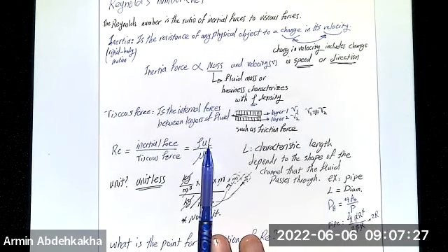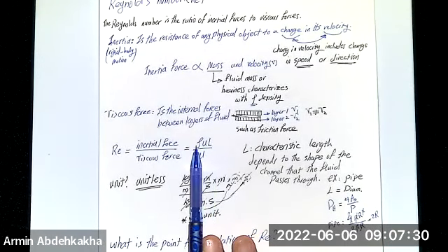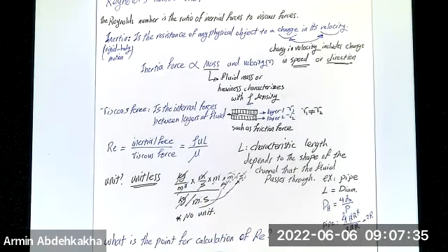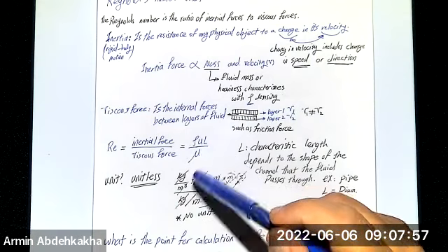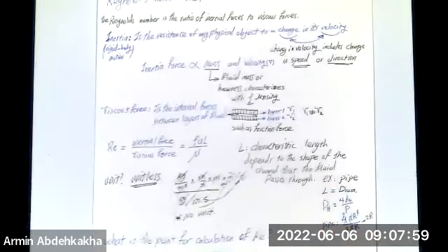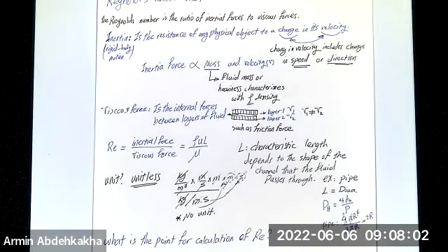If you multiply the characteristic length times the rho, absolutely the characteristic length has a unit of meter, but it shows that you already have a meaning of volume times density. So it gives you almost mass. Velocity gives you mass times velocity, which gives the meaning of inertial forces. And viscous forces depend on the mu. As you can see, you can prove how the Reynolds number is calculated, but it's not for you.